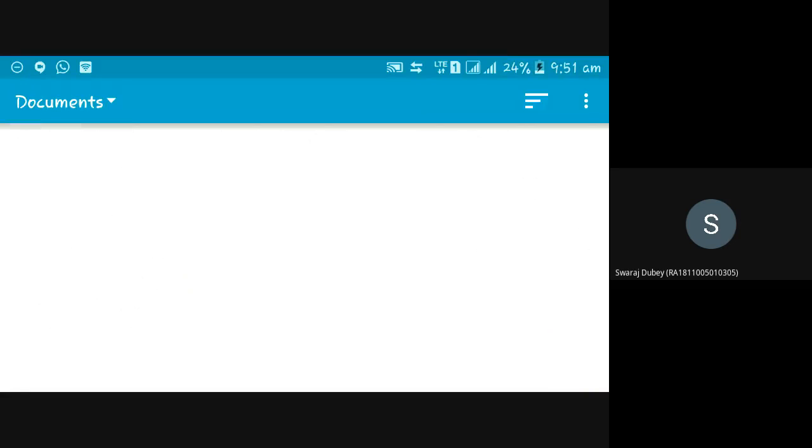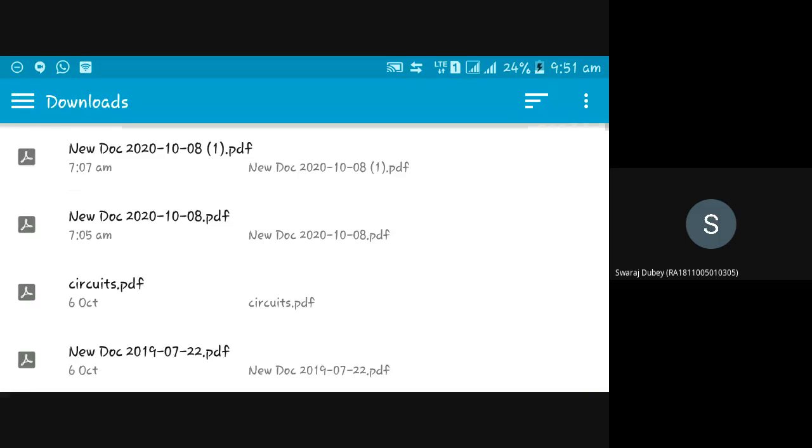So this is one last model. They may ask you to find gain margin, phase margin, or gain crossover frequency, or they will ask you to find out the value of K for which you need to shift the curve. Here they have given the gain crossover frequency. Similarly, they will give you phase margin or gain margin, and they will ask you to shift the curve. So you should be ready to solve any problems.